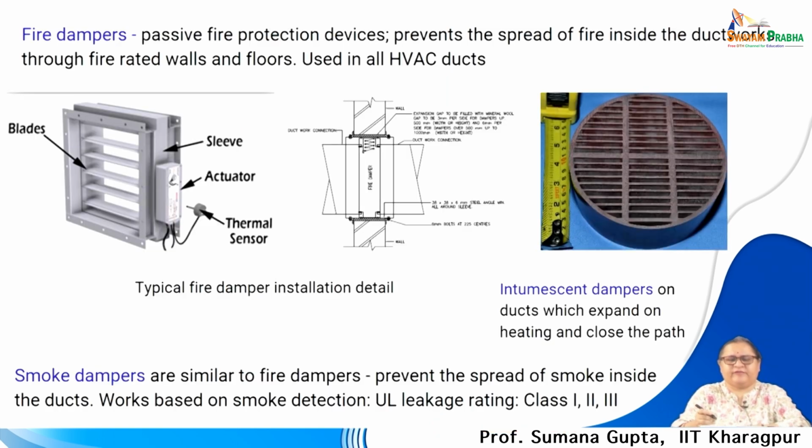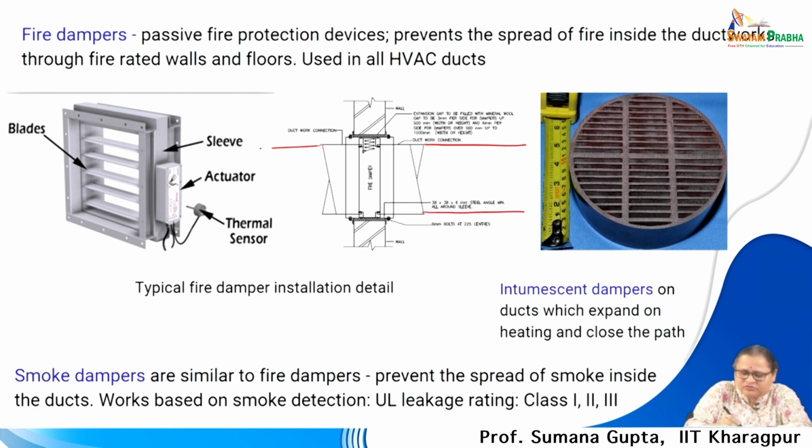Now, as we have talked about the garbage chute, we look into what can happen within an air conditioning duct. You see, this is the section of a duct. This side is zone A and this side is zone B. On this side there is fire, some fire has grown and some smoke is getting into the return air. I hope you understand the return air duct.